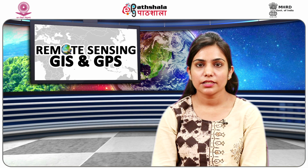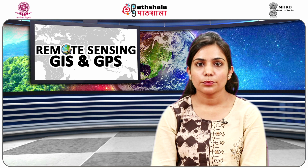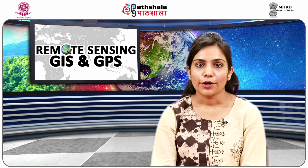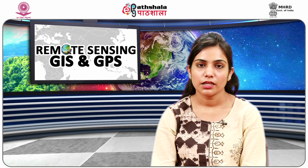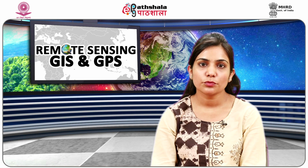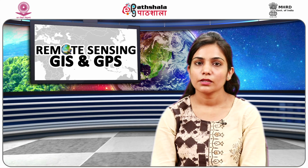Photogrammetric method has advantages of non-contacting 3D object reconstruction by means of spatial rays. It provides a short recording time on site, nearly independent from the amount of object points to be measured, and the possibility to choose the recording station in a very flexible way. If a dynamic or kinematic process has to be recorded, photogrammetry seems to be the only way to measure a whole object simultaneously. Next and the last application is military application.